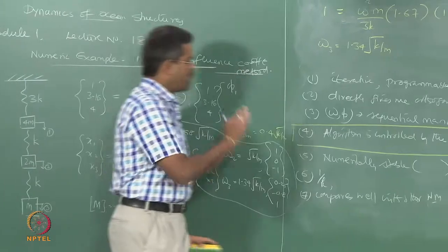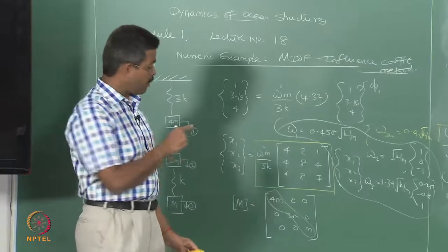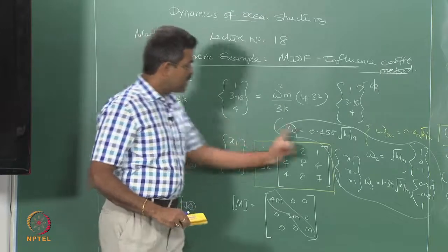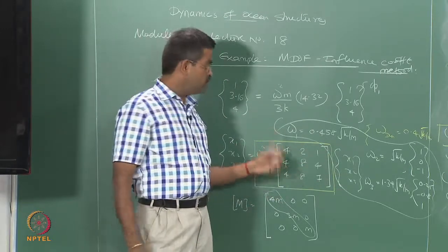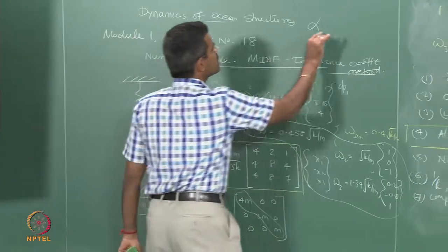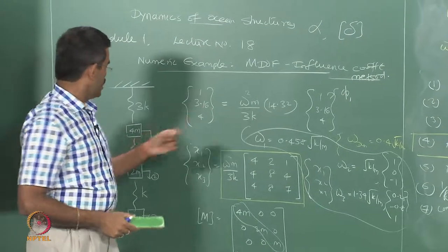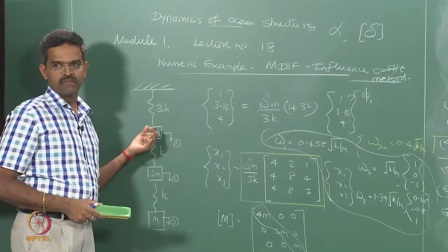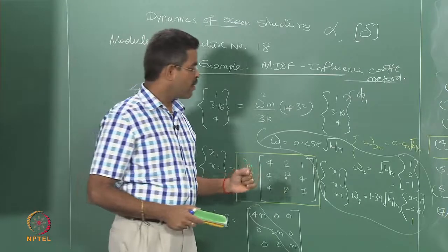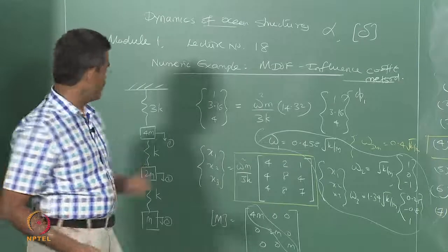So, these are some of the observations and experiences we have gained by solving a problem with this method. Now, let us get back to the algorithm, turn your pages and see. This matrix was not directly derived. You derived only the delta matrix using a series of spring system, then you multiplied that with a mass matrix and you got this matrix.